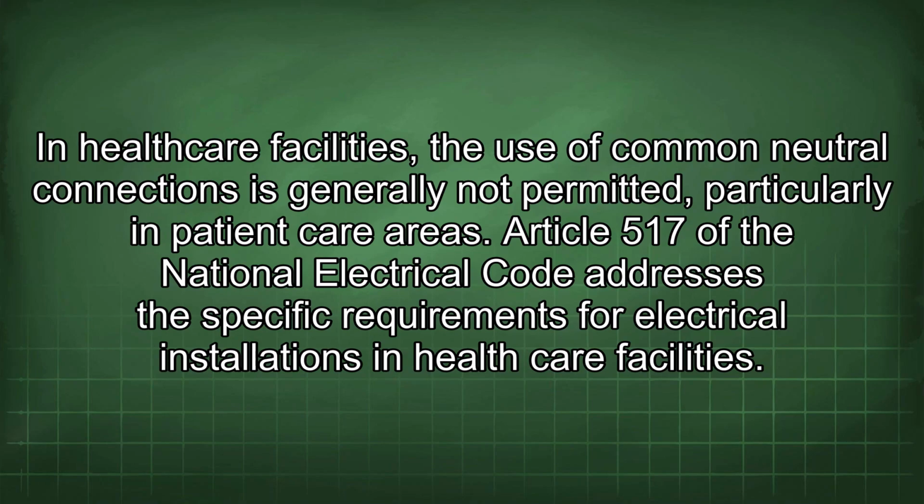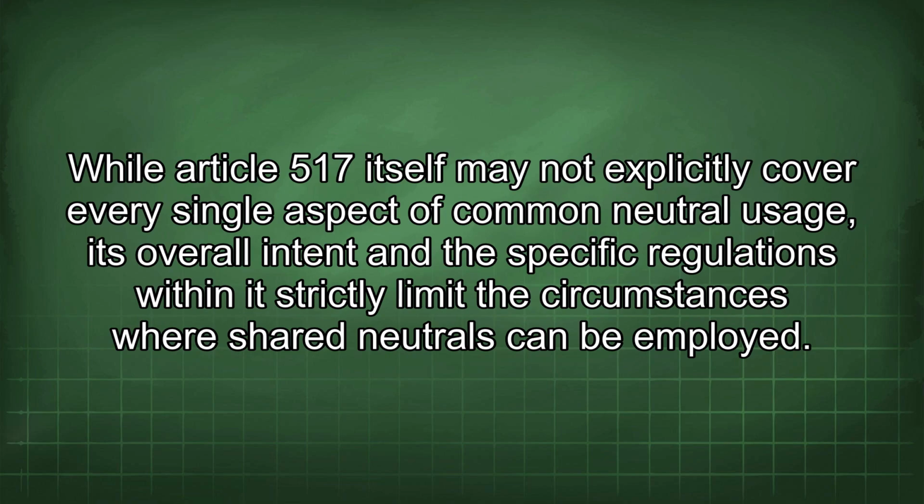In healthcare facilities, the use of common neutral connections is generally not permitted, particularly in patient care areas. Article 517 of the National Electrical Code addresses the specific requirements for electrical installations in healthcare facilities. While Article 517 itself may not explicitly cover every single aspect of common neutral usage, its overall intent and the specific regulations within it strictly limit the circumstances where shared neutrals can be employed.